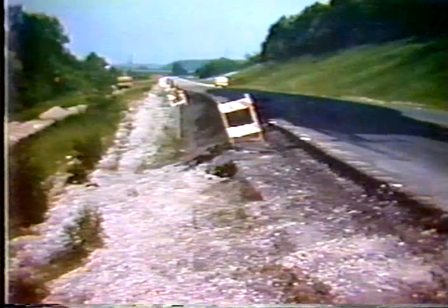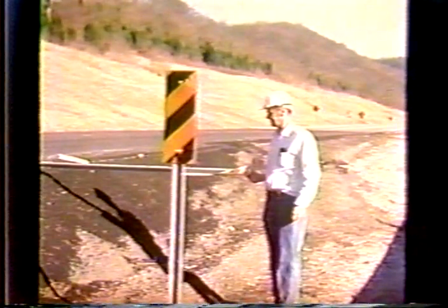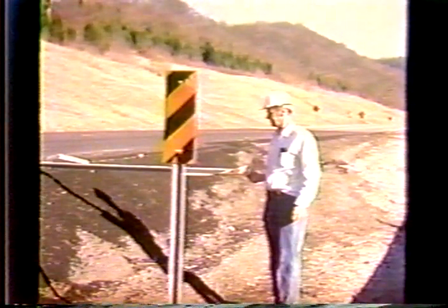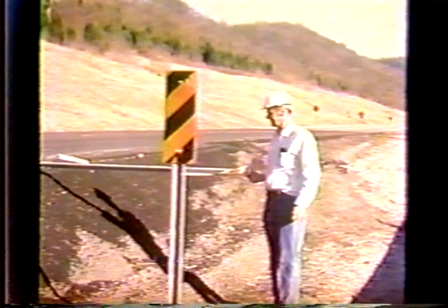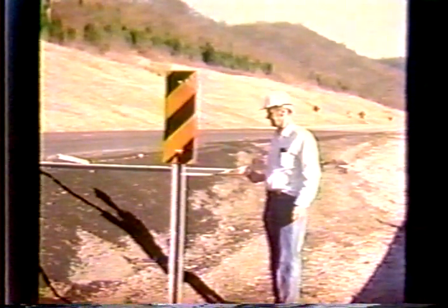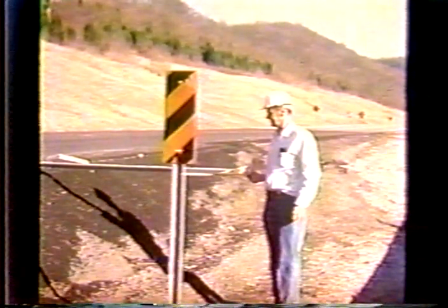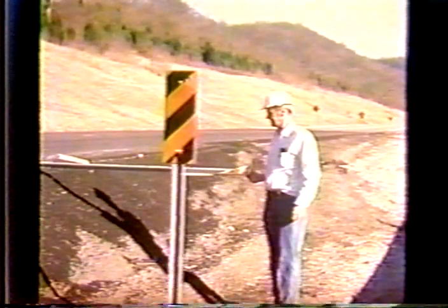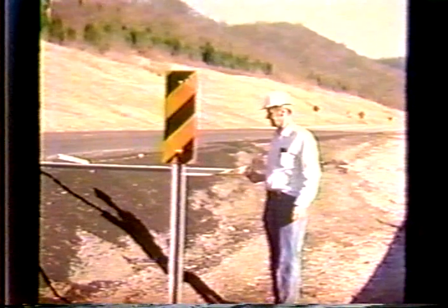Just an example application where the drainage blanket was used. This is a slide where maintenance had put in several feet of asphalt to try to keep the road open. Here again, I'd like to emphasize, don't let a situation get this far before you call the geotechnical staff or start looking for the causes of the slide, because when you get this type of vertical movement at the top of the slope, you've got a landslide, quite obviously.